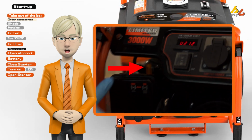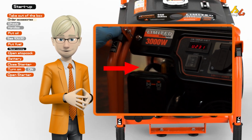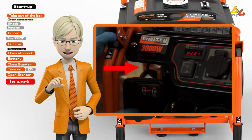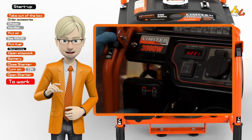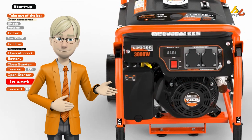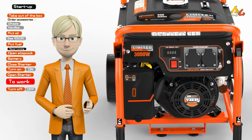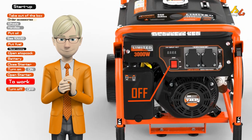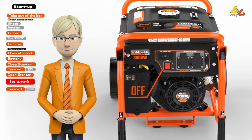When we've finished, we turn off the generator simply by turning the main switch to the off position, and we must remember that both at the startup and shutdown phases, there should be no appliances connected to the generator. If you have any doubts or problems during the starting of your generator, please contact our customer service team and we'll be happy to help you.